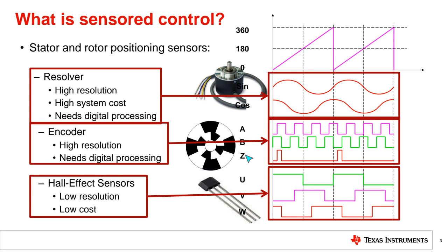Generally, we use a minimum of 256. A lot of the time, if you have enough money, and a high-speed circuit and microcontroller, it goes to 2500 PPR. What is PPR? If you use a Hall encoder, you will check the PPR number. PPR means pulses per revolution.